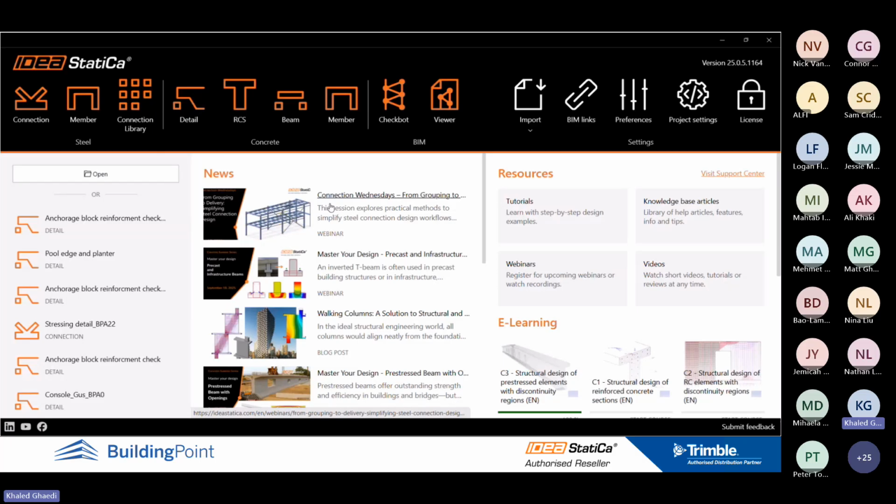So you can run the analysis, and then here you have the summarized result of the concrete, reinforcement and anchorage, under strengths and also under serviceability. If I go to the summary, as you can see here, you have the strengths in the concrete, in the reinforcement, and in the anchorage, all with the utilization ratio. And you can go to the strength. Here you can look at the stress limit check. You can look at the principal stress as well. If I go to the stress check value, which is actually the utilization ratio for the stress, you have the principal stress, the principal strain, and also the plastic strain as well. And also you can look at the direction of the stresses as well.